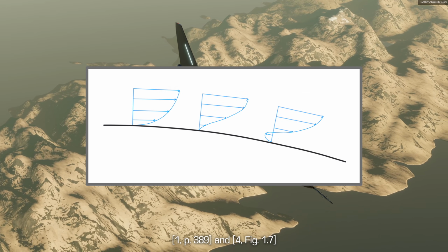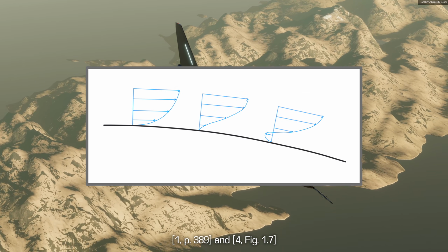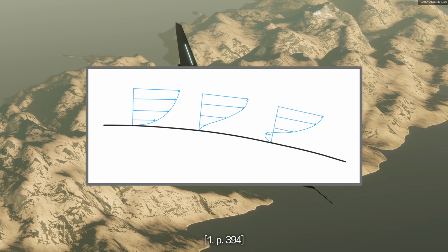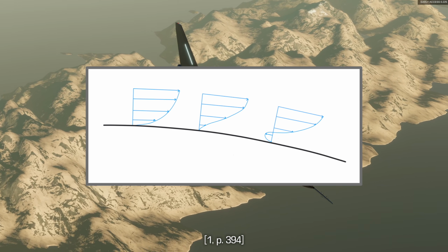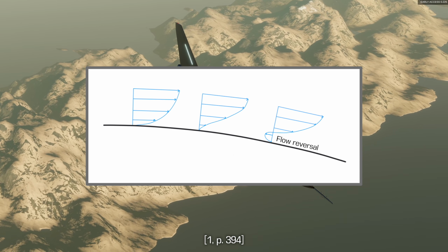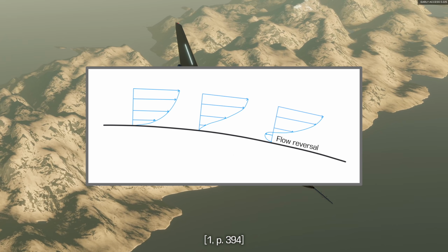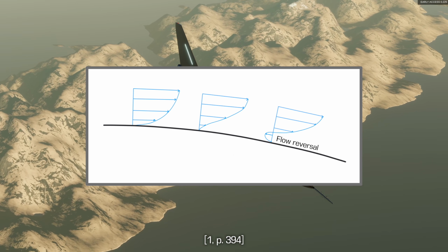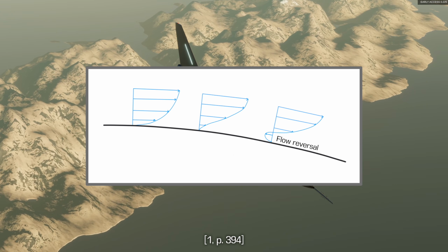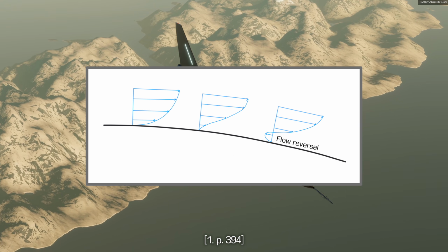For the incompressible case of flow around an airfoil, pressure drag will only occur if there is flow separation present. Flow separation occurs on an airfoil when the air particles influenced by the airfoil begin to reverse direction, which typically occurs when the air is moving relatively slowly while also experiencing an adverse pressure gradient, which is when air pressure begins to increase along the path of the airflow rather than decrease.